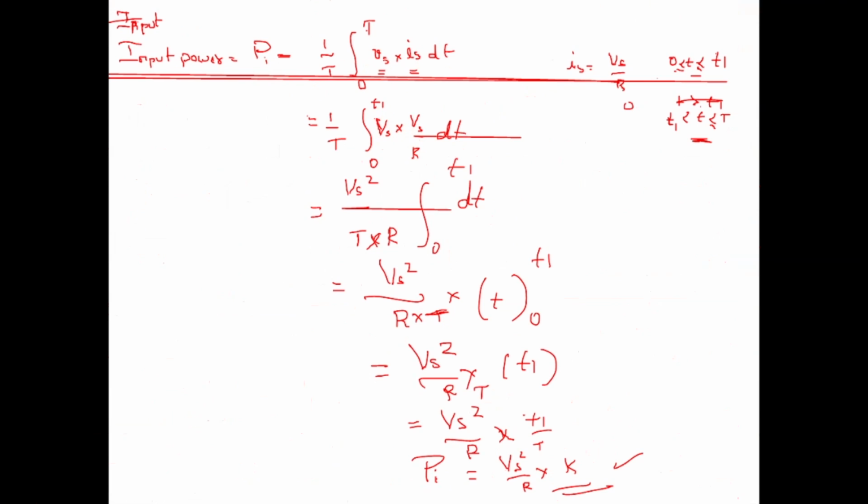Here, what is the instantaneous value of the source voltage? Source voltage is same, Vs. What is the instantaneous value of the source current? Source current means what? The entire source is not responsible for current, because from that source Vs, some drop occurs while current is flowing through its switches. That is how much? 2 volts.